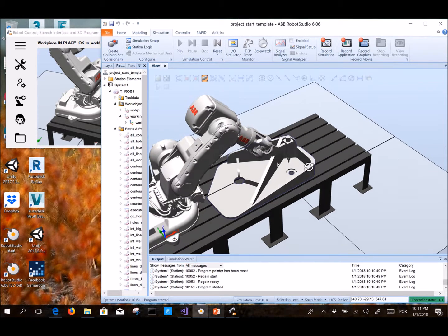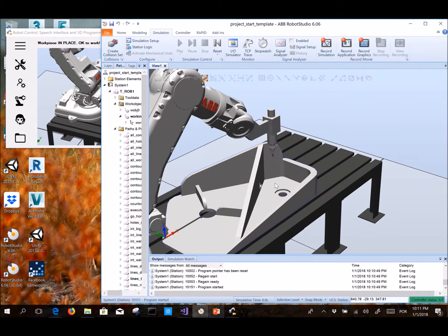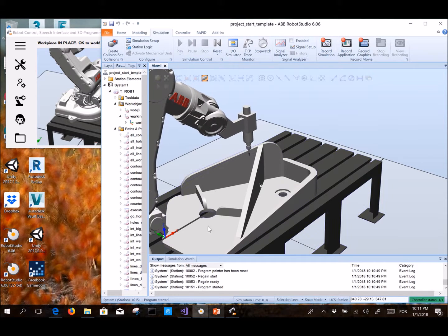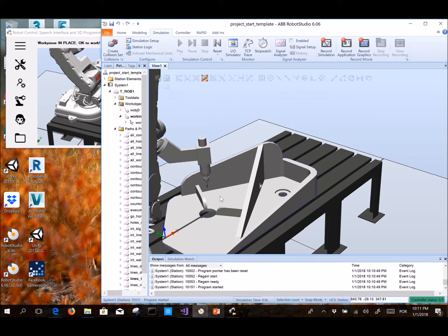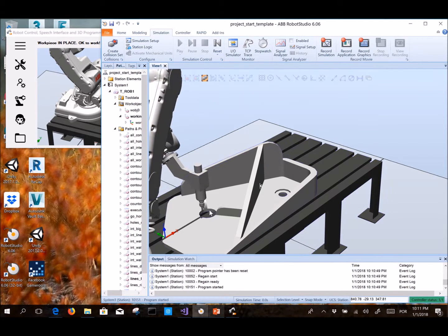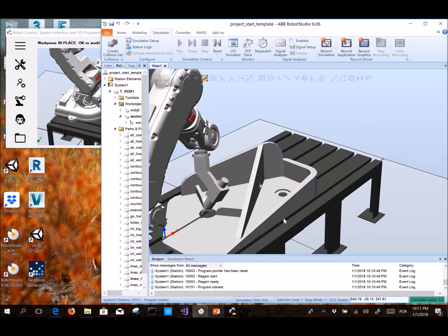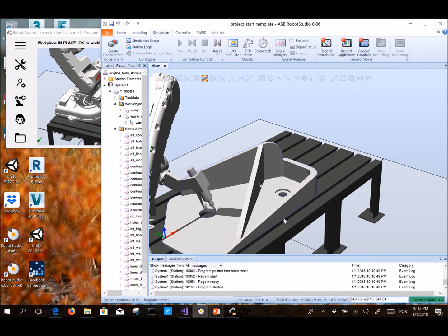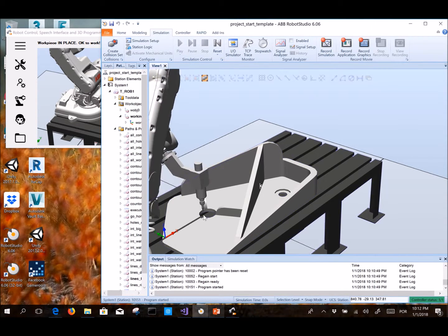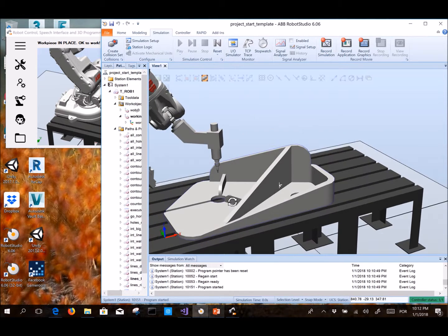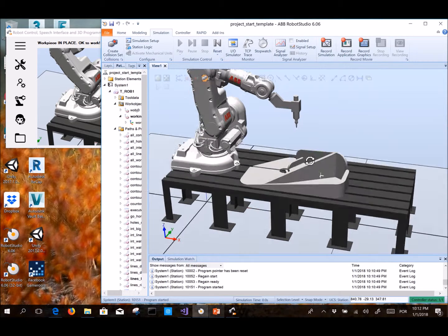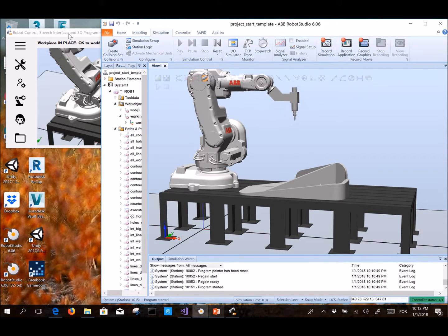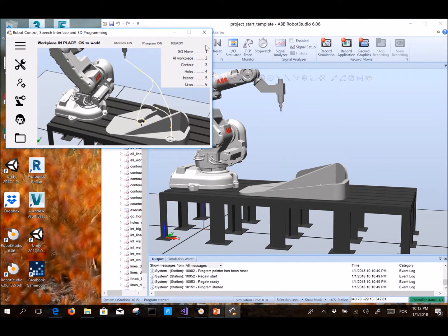I can show you what it is doing. Then it goes to this hole here. The velocity in the program here is 1,500 millimeters per second, but of course the simulation goes slower than that. The one selected is this one, and in contact I'm selecting 200 millimeters per second. So you see, the simulation stopped. It's going home now. So when my application goes home it stops, and I have the menu available again.